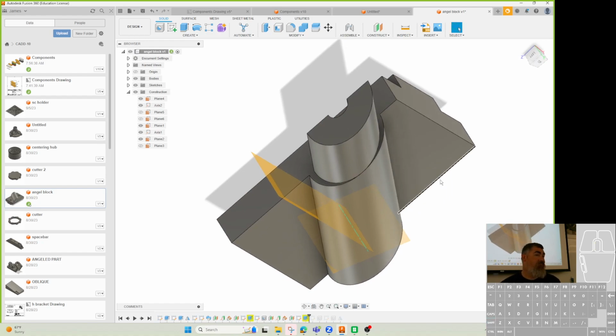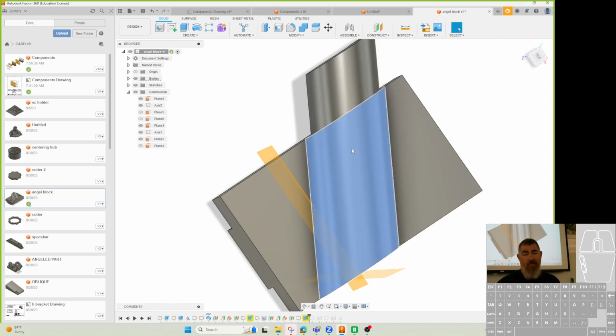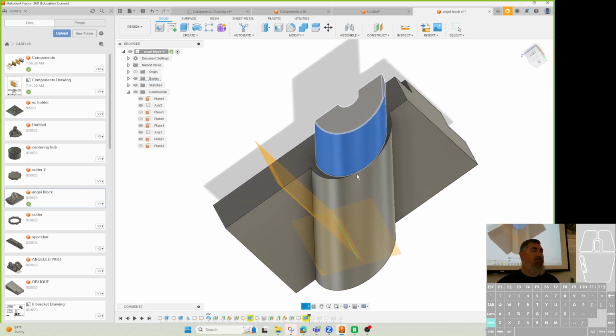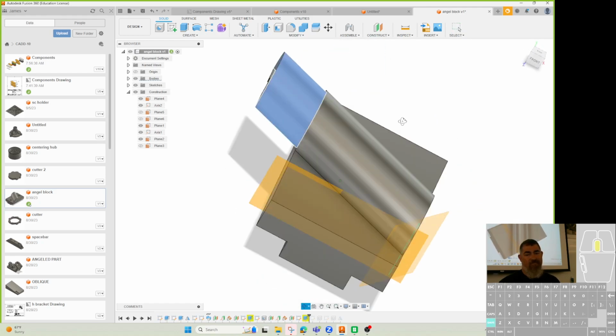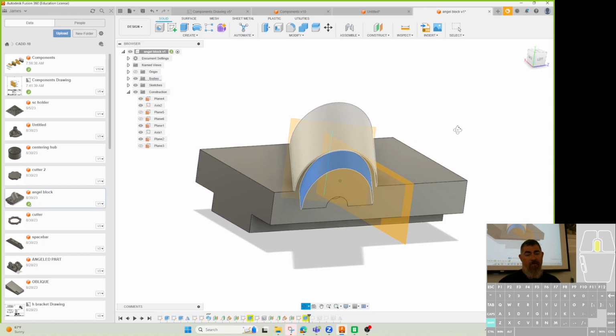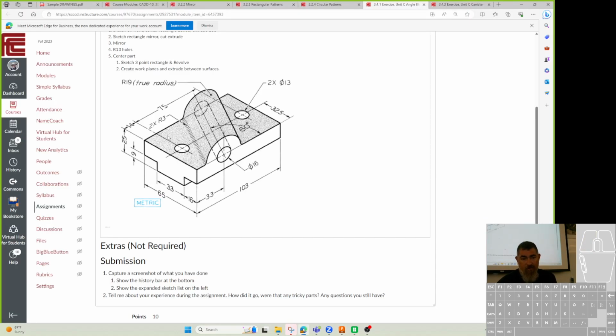Yeah, and so they might not see right away, but when they put a radius gauge on it, instead of being the right radius, instead of being a radius 19, it would be a lot smaller. So that's part of the process: you'll make one, try it out, and measure everything. Because when you're out in the real world, whoever's making the part has to check things, and they'll see it says true radius on there.